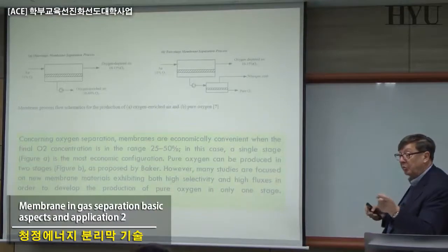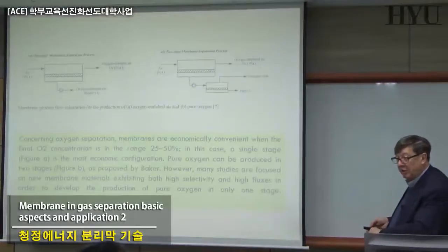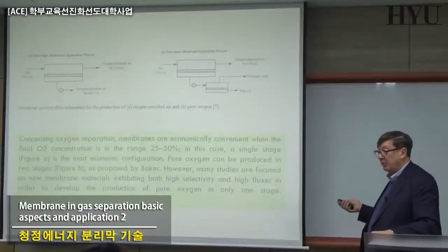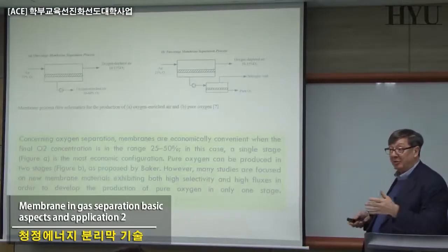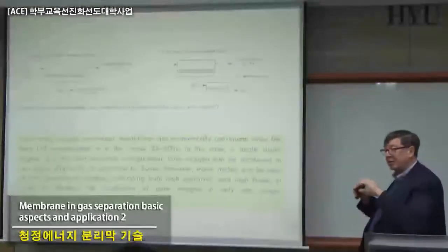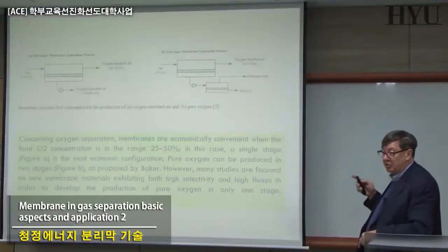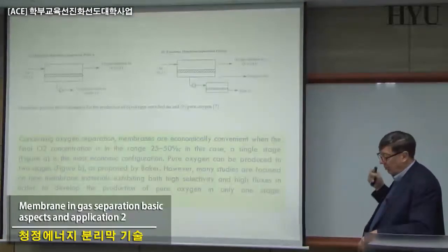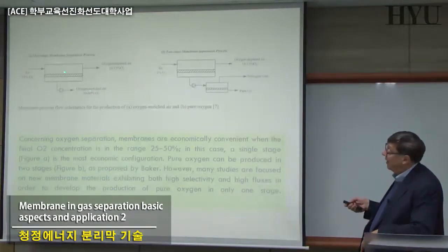The day that you will produce at decent cost industrially perovskite membranes, do you know what are the perovskite membranes? Membrane in which there are no polymers, no rubbery, no glassy, just crystals. And normally we don't like to have crystal because crystals are barrier to the separation. But perovskite is a very special case because we are using defects present in the crystal structure for having the transfer only of the species related to the defects. For example, you can have a situation in which there is a vacancy for hydrogen, so hydrogen can go through very quickly, or for oxygen eventually. So in this case, you can have also single step.